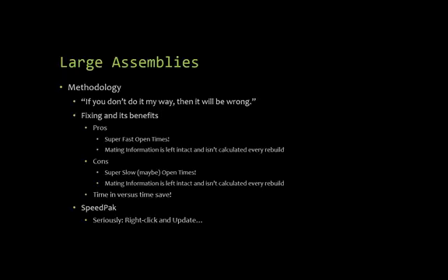So basically, if you go through and fix it, and if I take a look at my assembly here and go look at my mates, now I am using sub-assemblies as well, which is always a good thing when you're dealing with large assemblies. But you can see that all of these have an F next to them. If you suppress a mate directly, it'll just gray out. But if it gets suppressed because a part is being fixed, it's going to gray out just like it does, but it's also going to have a little F next to it.